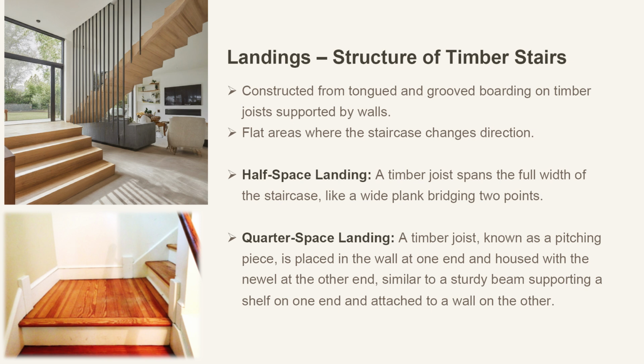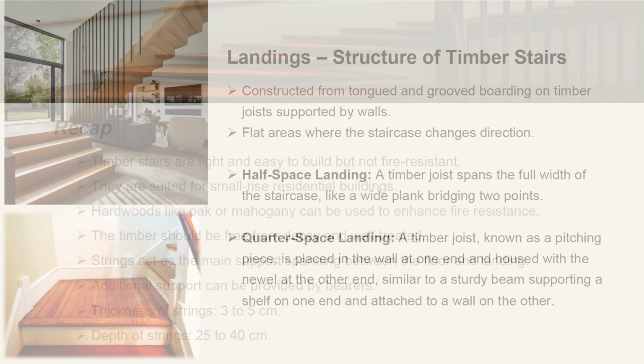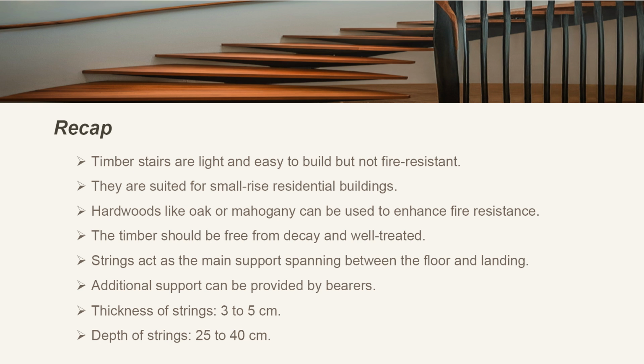Hope you could visualize all these from the figure. Let us take a quick recap now. Timber stairs are light and easy to build but not fire resistant. They are suited for small rise residential buildings. Hardwoods like oak or mahogany can be used to enhance fire resistance. The timber should be free from decay and it should also be well treated.